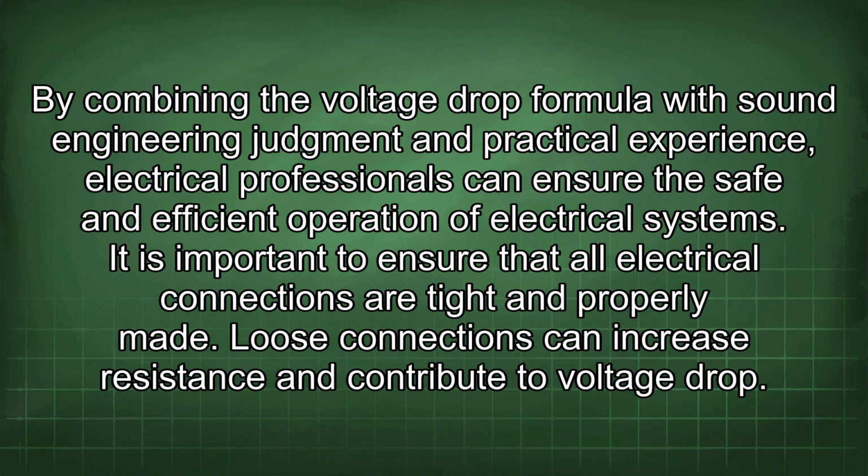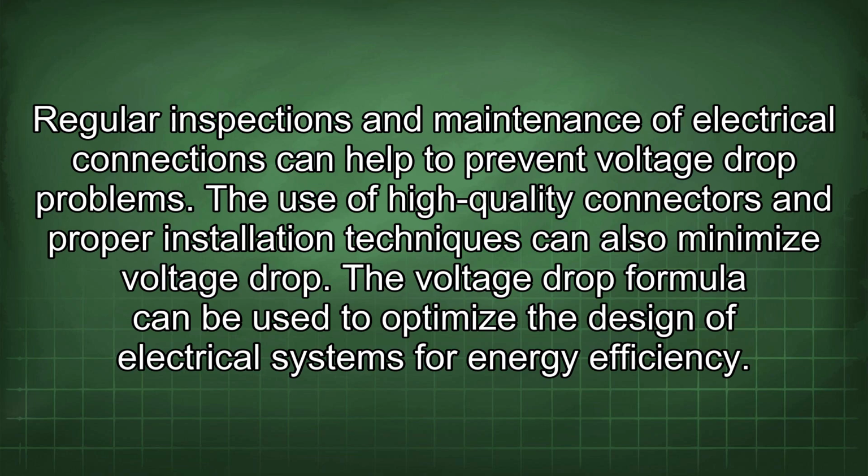It is important to ensure that all electrical connections are tight and properly made. Loose connections can increase resistance and contribute to voltage drop. Regular inspections and maintenance of electrical connections can help to prevent voltage drop problems. The use of high-quality connectors and proper installation techniques can also minimize voltage drop.